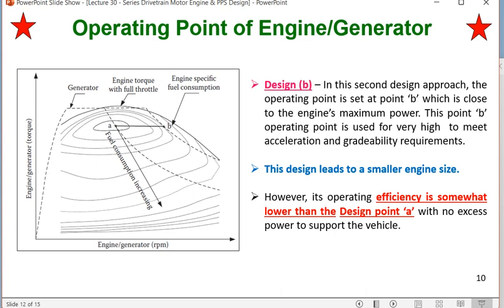For very high speed and a very short time from source to destination, we are not going to keep our speed within the optimum region of A. We are going to accelerate the vehicle as much as possible, in the highest gear. We shift the speed from A to B. We get very high speed from the vehicle, but efficiency in that case will be lesser.